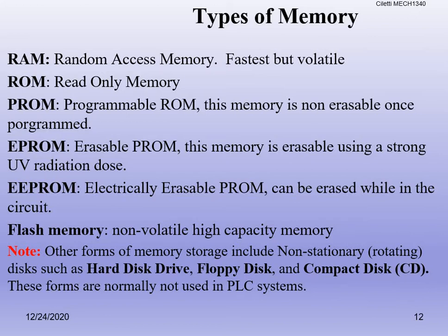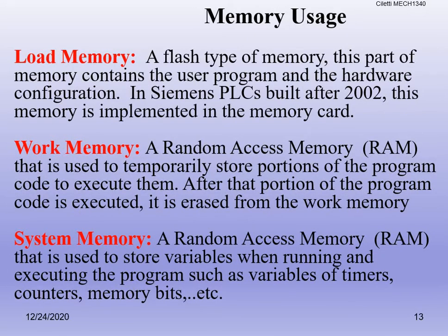So we use flash memory. It's non-volatile, with a high capacity. That's our little SD card that's going to be sitting inside our PLC, same thing as a thumb drive or things like that. Our programs, when we download them onto the PLC, are going to go onto the flash memory, onto a little card. So I could pop that card out, go to a different PLC, put it in, and be running the program that I have on that card. So load memory, that's the flash memory.